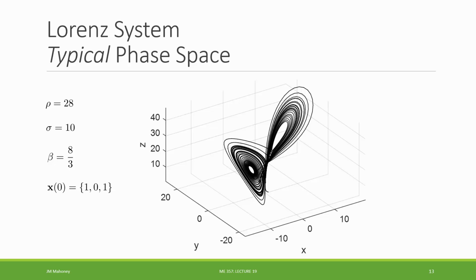Now this is a little bit different than the linear system we looked at before, because given enough time, in our linear system the energy dissipated out and we got to some equilibrium position. This nonlinear system is different, in that we're not really losing, let's say, energy in the system, generic energy. This will keep rotating around over and over again, as we're going to be seeing in the animation, and it's not going to settle to one constant value in this case, but it will keep repeating around these points.